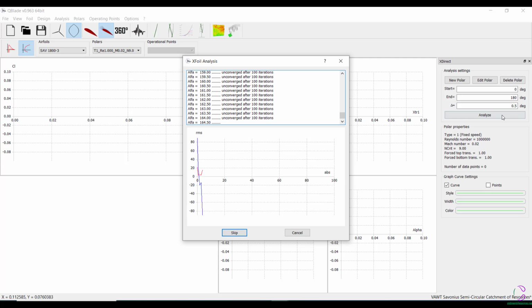When you are modeling a Savonius VAWT in QBlade, you will realize that you are going to get CFD, which is computational fluid dynamics, the lift and drag information for this airfoil or profile within 170 and 180 degrees, meaning that the typical area for where you have the angle of attack for the regular airfoils, you do not get any reading for a Savonius drag in QBlade.